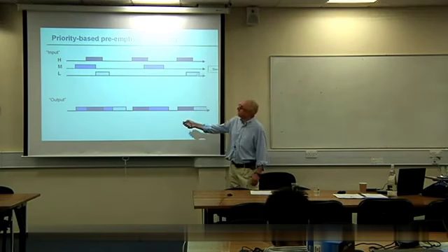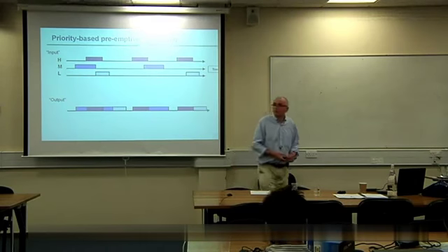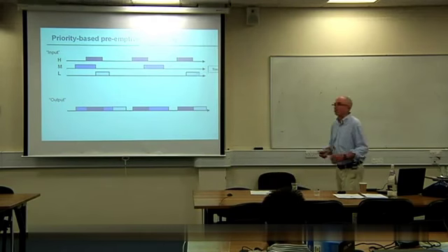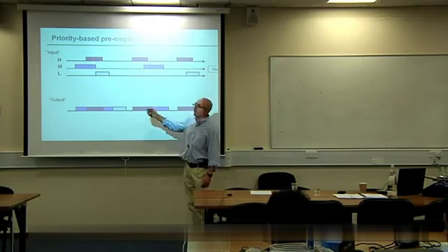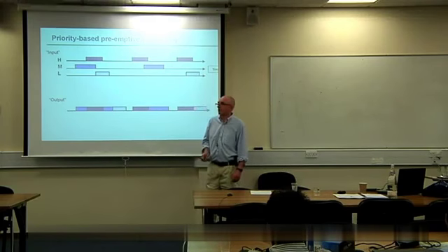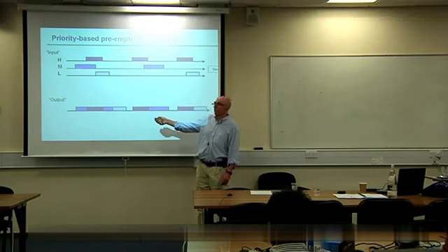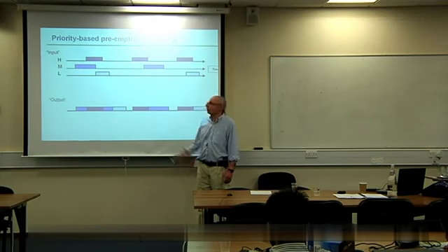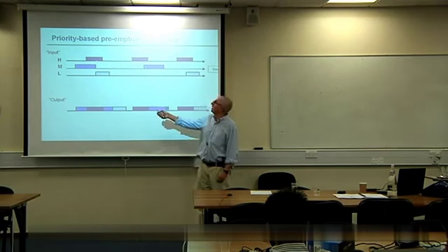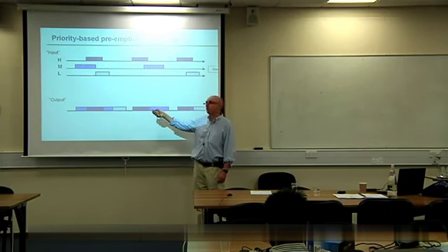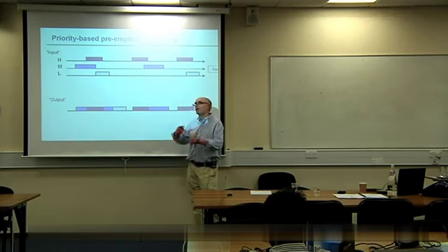Suppose there are two shared resources in the system, and they share two different shared resources. Then what we've decided to do is give this one the higher priority all the time. But then we just repeat the problem later on in the execution when it comes to the second shared resource, when this, which is now the medium priority task, would be blocking the new high priority task.